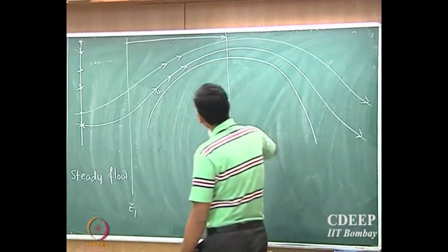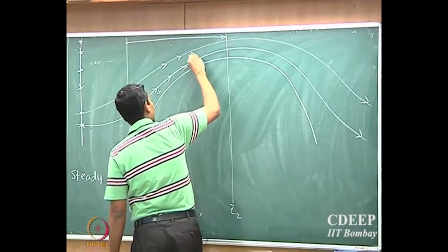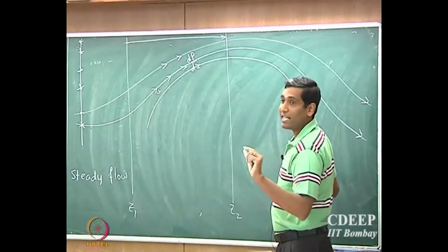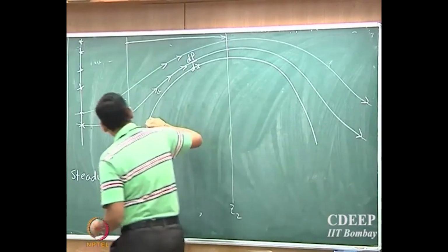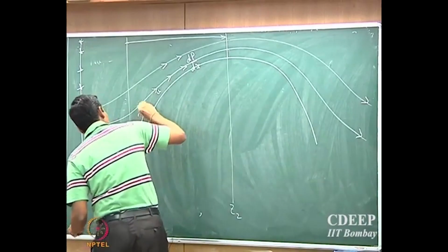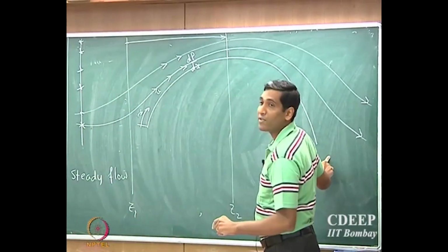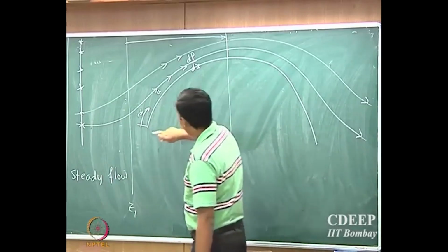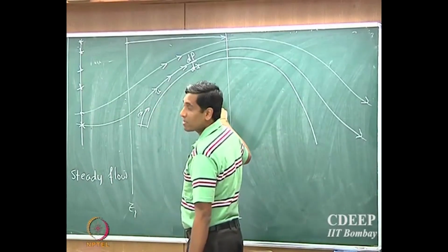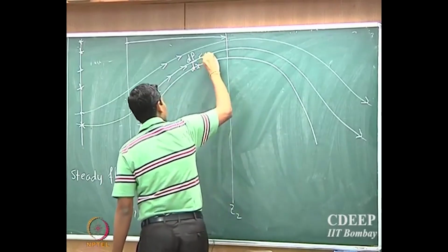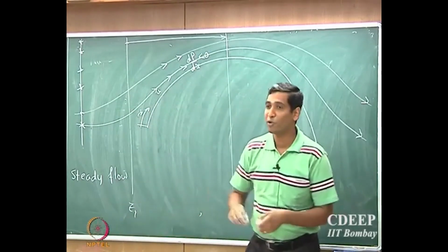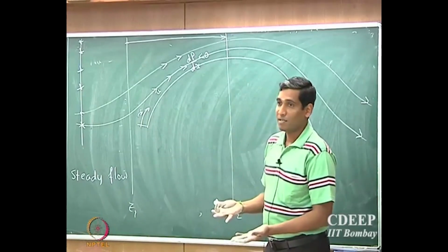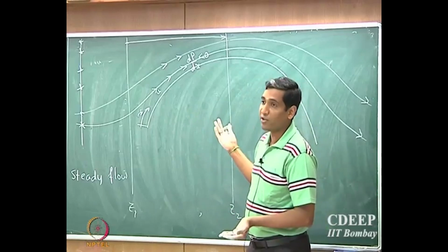So, if you look at the pressure gradient, note that here the x coordinate is the curvilinear coordinate, not the linear coordinate. So the x direction is the location along the curved surface, and so dP/dx along the curved surface has to be less than 0 in order for the fluid to accelerate. Now that's not true everywhere. This happens only till a certain location.